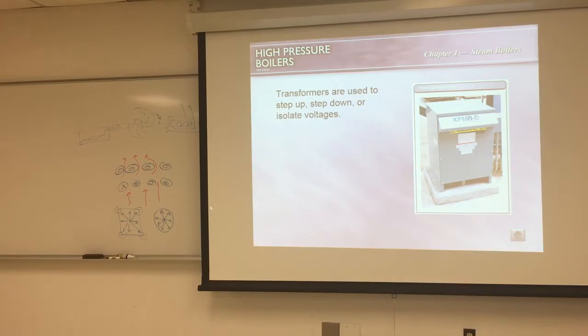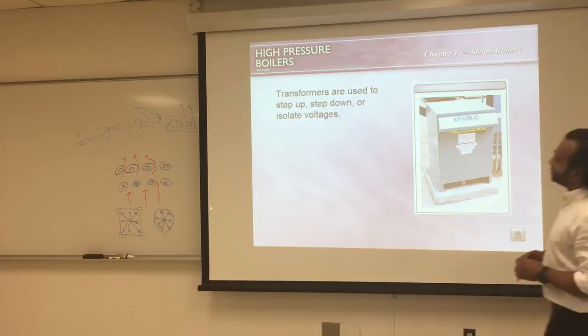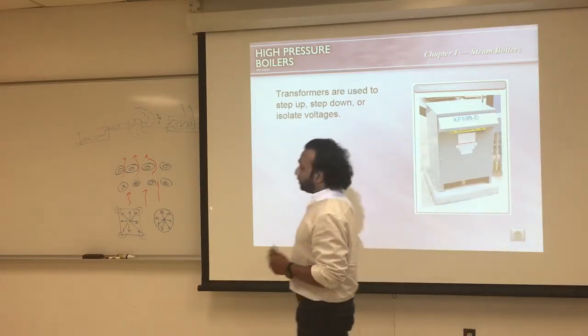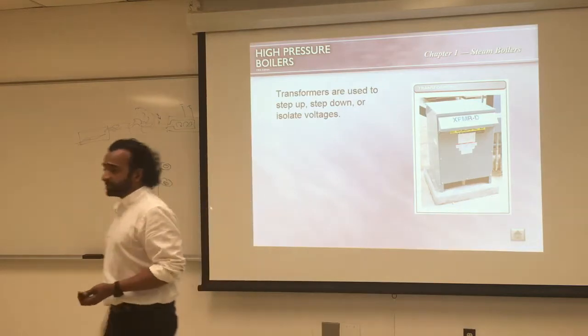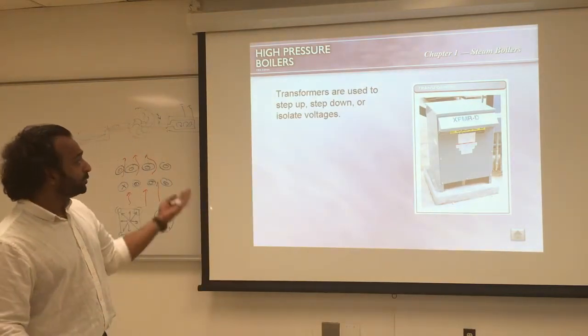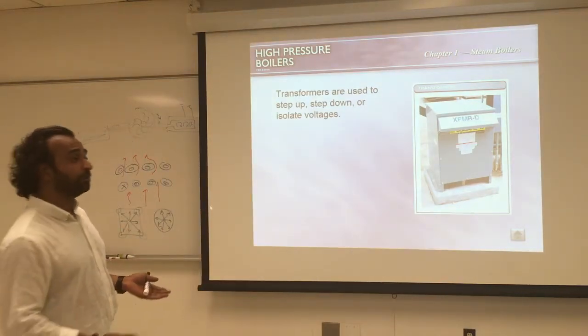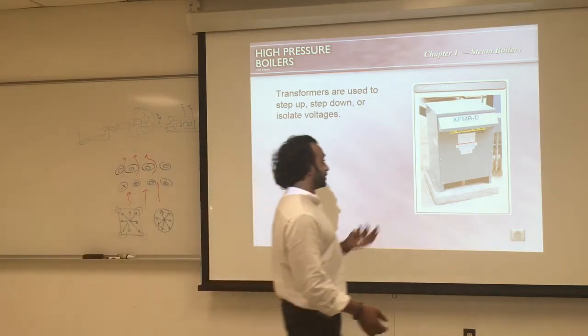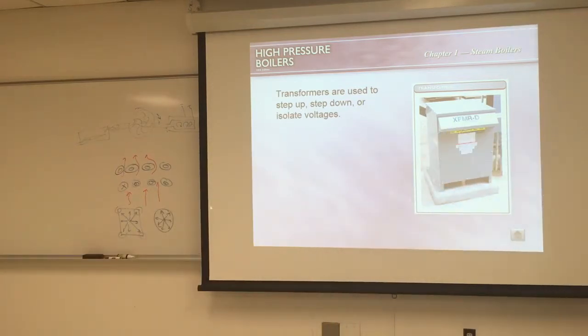Transformers, probably you've seen these in your neighborhood or district. We have some here in the lab. They are used to step up or step down, or sometimes isolate voltage. So you get like 4,000 volts, and these will transform the 4,000 volts into 400 or 120. So you'll see probably one for each neighborhood.